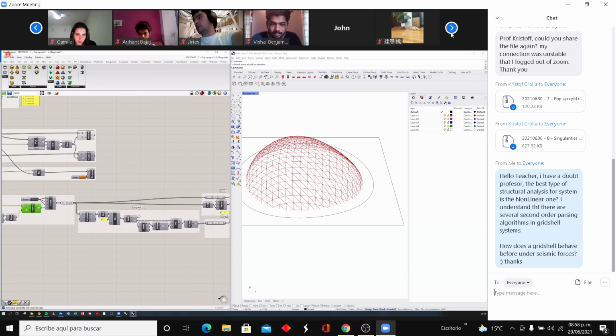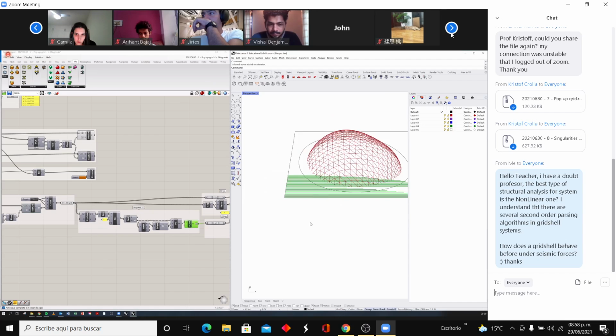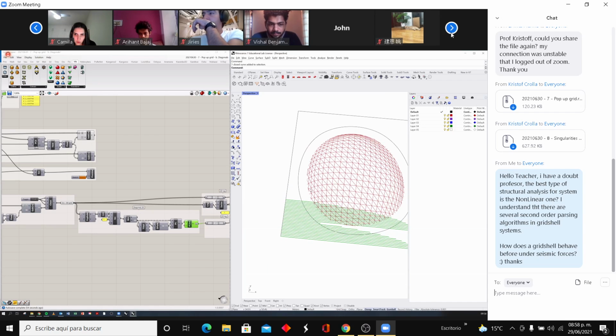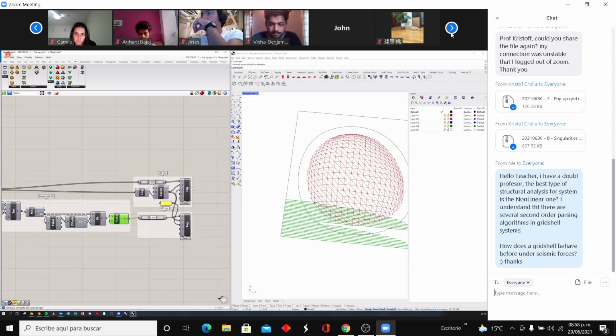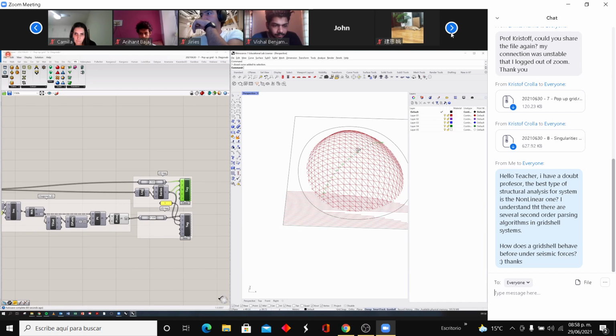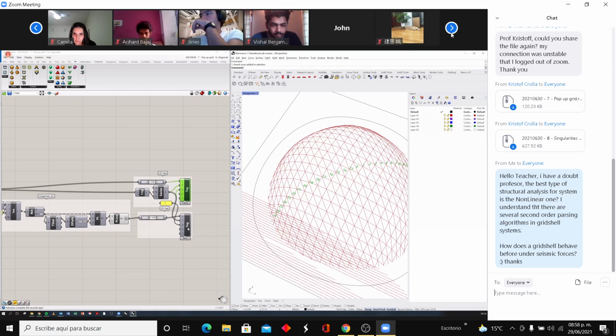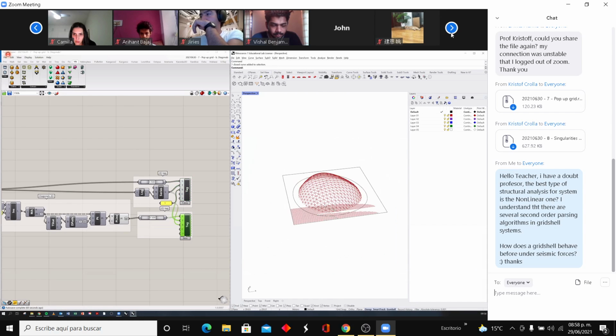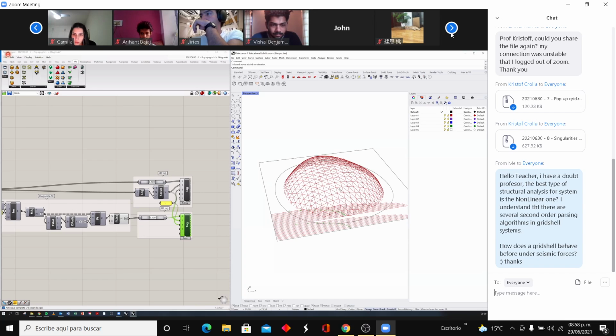And then the only thing I'm doing after that is, let me quickly see. Yeah, measuring the lengths and producing polylines on the ground here according to the lengths of the diagonals that I have produced over there. Similar to what we did yesterday when I was doing the unrolling. So nothing too complex there. And then I just added 3D tags to the three-dimensional diagonals here. So here you see the order and the ones that we have at the bottom. So it's a very quick system because we're just relying on the control points that we have drawn up already. So it's quite straightforward to do.